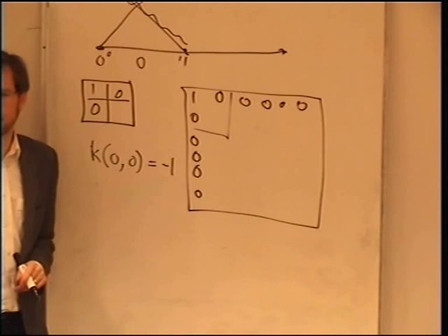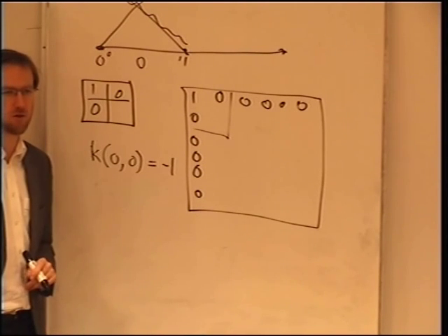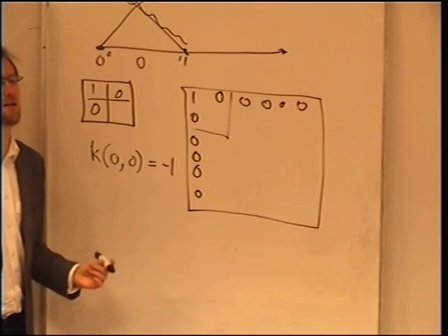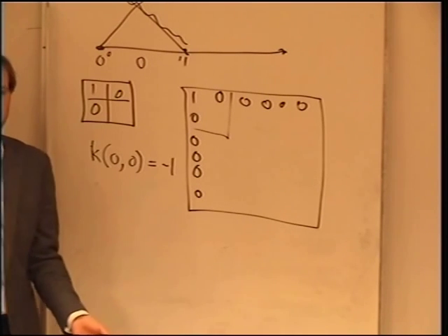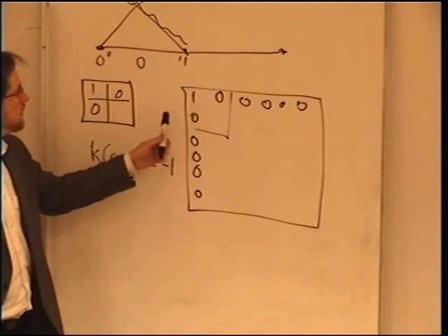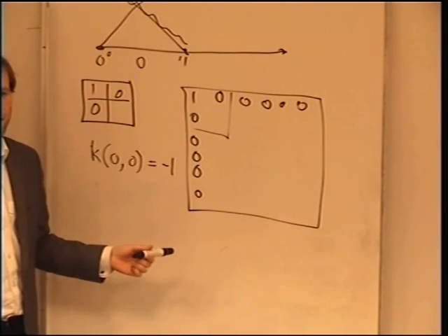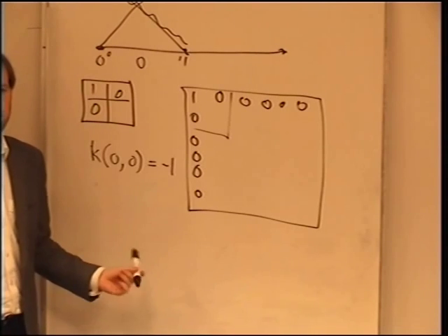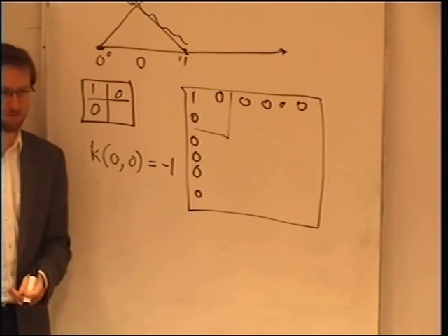The reason we do that is that there's a handy feature of PETSc, which is the thing we use to assemble our matrices: if you tell PETSc to insert into an entry in your matrix, and either the row or the column you specify is negative, it just throws away the number. It doesn't do the insertion.